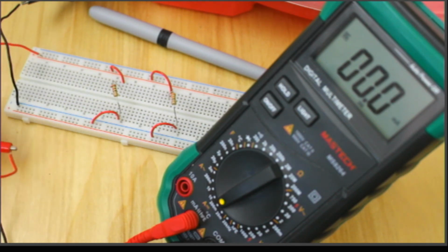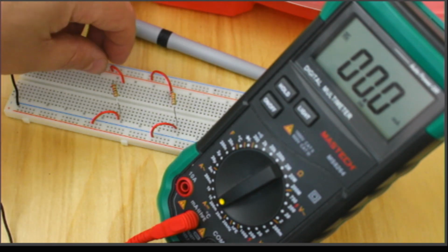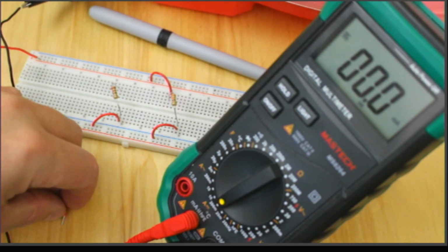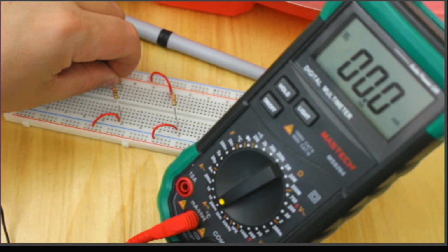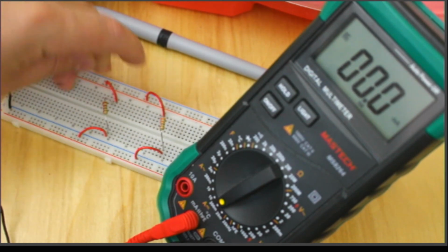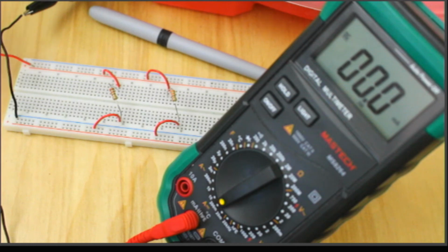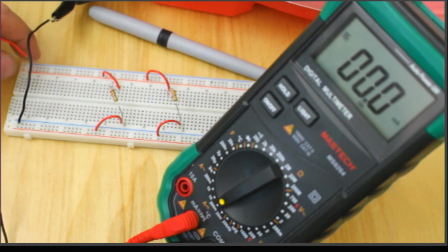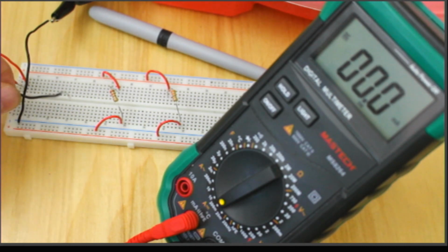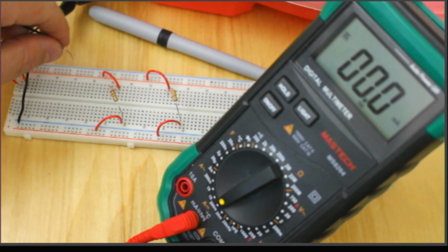So I'm going to measure the total circuit current first, and I'm actually going to do that. Let's see, up here at the very top, I'm going to take this out. Okay. Actually, I'm going to leave that in because I need to draw that current too. Put that back in place. And so what I'm going to do now is I'm actually going to take the positive terminal and put it over here. And so now I can connect the red terminal of my meter to the positive terminal of the battery, and then take the other side of my ammeter and now go into that top rail,